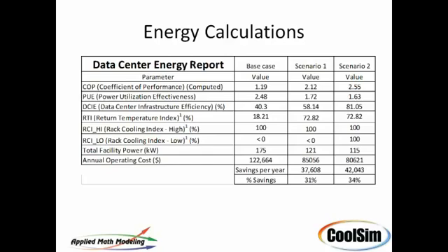The most important factor there is the coefficient of performance going up to 2.5. So things improved. You want that number to get as high as you can. Remember, it is the ratio of the rejected heat compared to the amount of work. So as the amount of work declines to get that rejected heat, the number rises. No cooling at all, you've got a COP of infinity. In other words, no heat pump. You've got the window open.